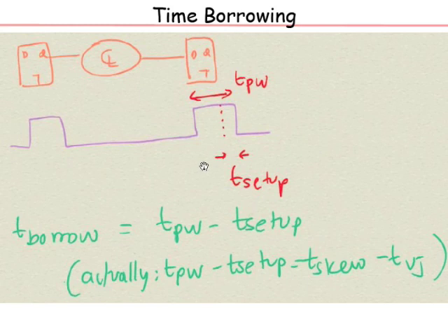But in search for speed and quick time to market, these are things one has to do. The reason is quick time to market is because when something like this happens and you do a reanalysis and you say, look, it's okay for me to violate timing a little bit because I'm going to borrow time from the next stage, and the design is okay, you kind of ship it. Instead of redoing the layout, because that process of closing timing can be very time consuming, because physical design goes back. Sometimes if you have to go and change the complete microarchitecture, change the pipe stages, that can be the worst, because it will take a long time to go back and converge. So that is where this also has some benefit.